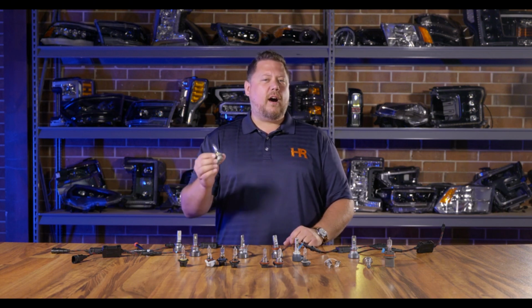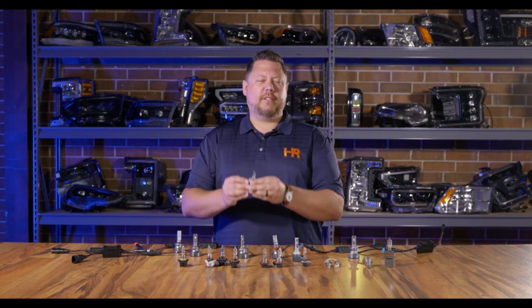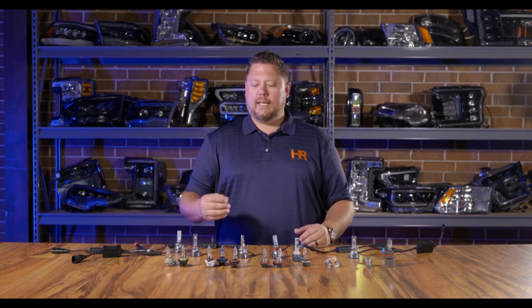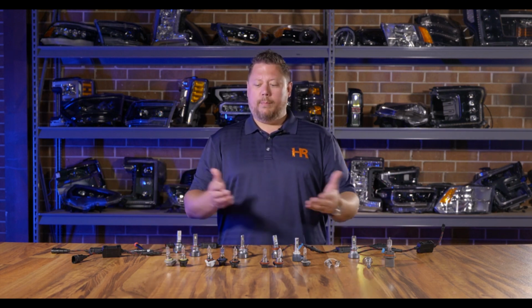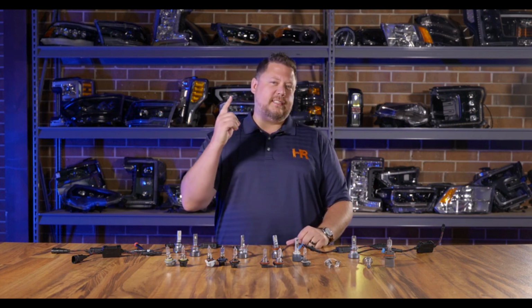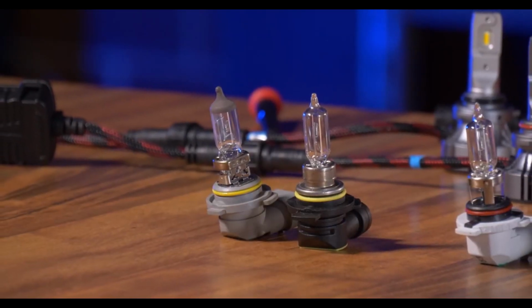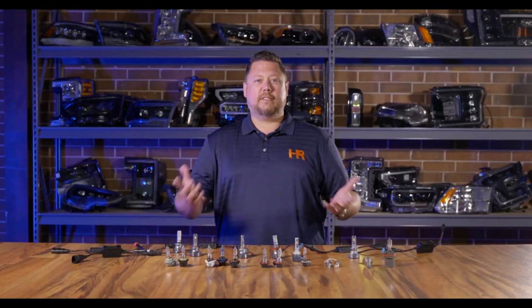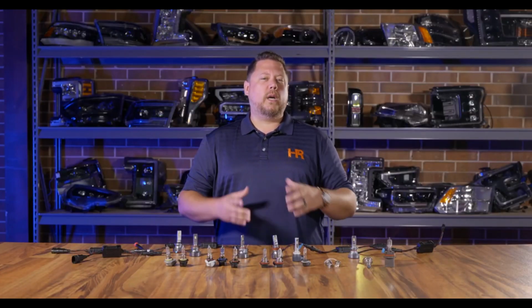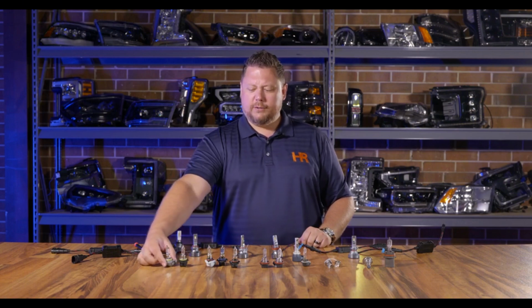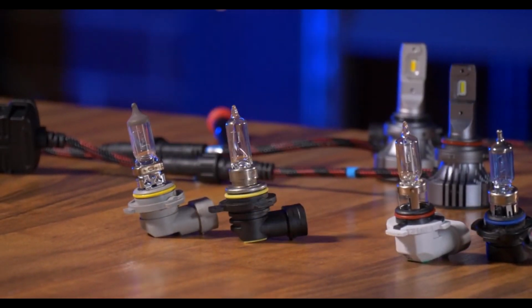That's because auto manufacturers use many different names for the same or similar bulbs based on the application. You're going to get a brighter bulb or a less bright bulb based on that part number. Now, aftermarket bulb manufacturers just take the standard size and say this 9006 fits 9006, HB4, 9012, etc. So the first thing you have to do is figure out what you have and then figure out which bulb is compatible with yours. So for example, we have a 9006 and a 9012.